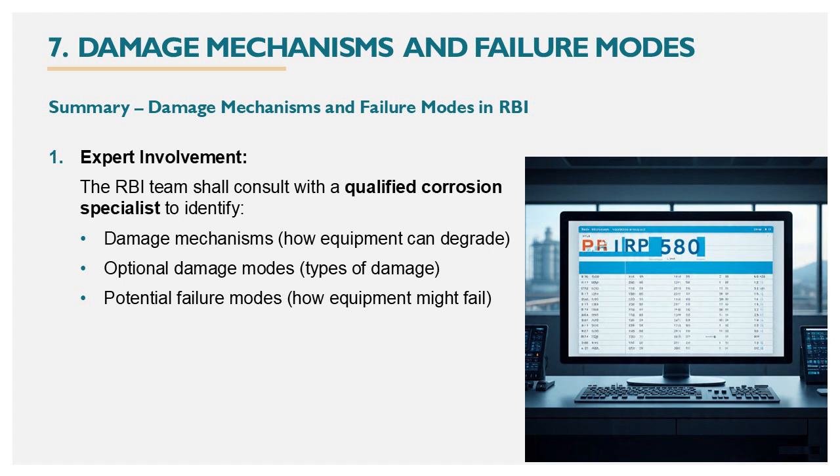Summary of damage mechanisms and failure modes in RBI. Number 1 is, expert involvement. The RBI team shall consult with a qualified corrosion specialist to identify, the first is, damage mechanisms or how equipment can degrade. The second is, optional damage modes or types of damage. The third is, potential failure modes or how equipment might fail.